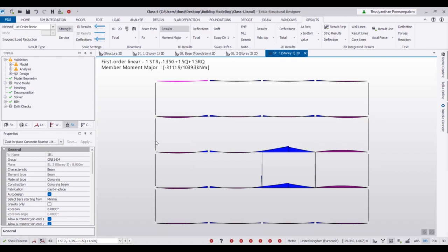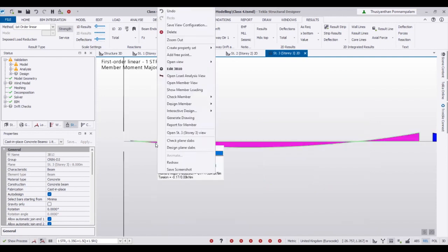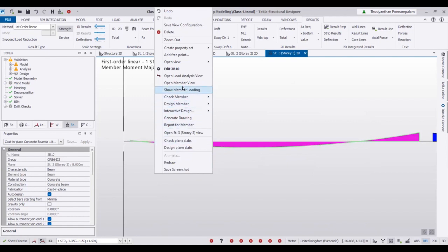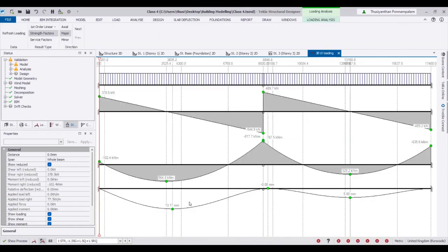Here I showed you one. This beam, let's go and see this beam. Here you can see a small bending moment. Actually, it's quite a significant bending moment because this joint I did not make it pin. In the model, I did not make it pin. So this is considered fixed and transferring the moment. See here, I am transferring a very big moment, more than our span moment. It's a very big moment being transferred.